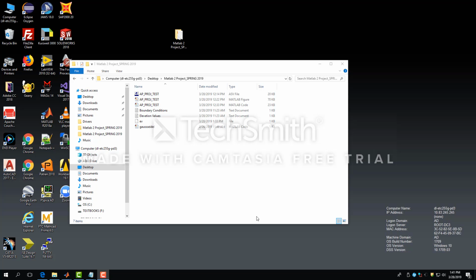The boundary conditions should be set as -1 for a constant flow boundary, 1 for a no flow boundary, 2 at the node that contains a well or pump, and 0 for all other active nodes. If you have a well or pump, please input the flow rate in the corresponding node in your constant file. I'll go ahead and click on the constant file and boundary file to show you something similar. So now I will show you our example for the conditions and elevation values.